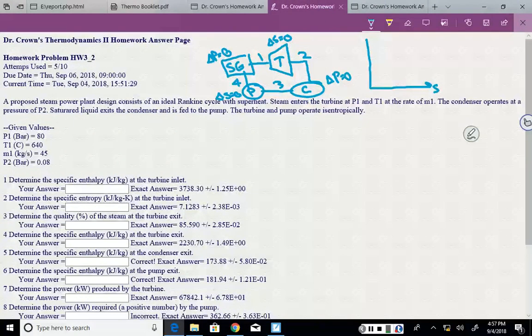So on a pressure-entropy diagram, it would be a square. In the turbine, there's pressure drop at constant entropy, and then a reduction in entropy in the condenser until we're at a saturated liquid. I'm not going to draw the saturation curve here. And we just have a rectangle, square, depending on the units. So state 1, state 2, pressure drop. State 3, constant entropy to state 4. The pressure drop from 1 to 2 has to equal the pressure rise from 3 to 4, obviously, if those are two horizontal lines. So there's only two pressures, P low and P high.